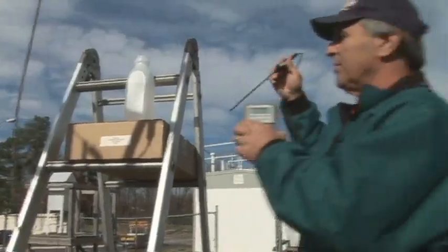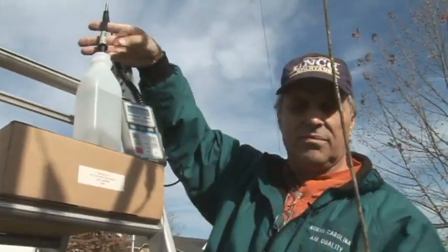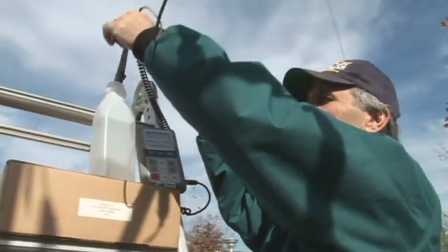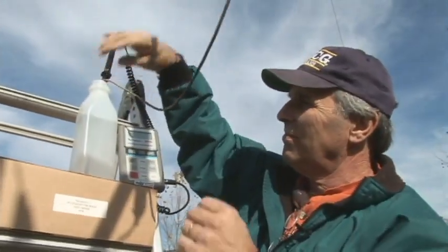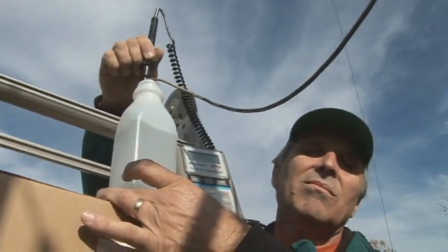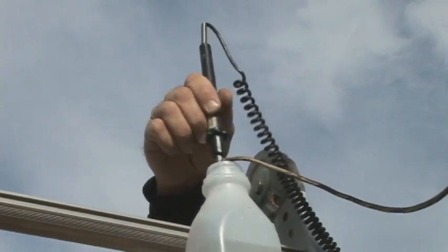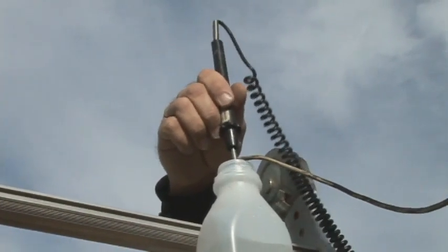The outside technician heats water to approximately 40 degrees centigrade. He then dumps out the ambient temperature water and pours the hot water into the container. With the hot temperature water in the container, the probe and thermometer are placed in the water bath. The outside technician should stir the water to avoid pockets of different temperatures.